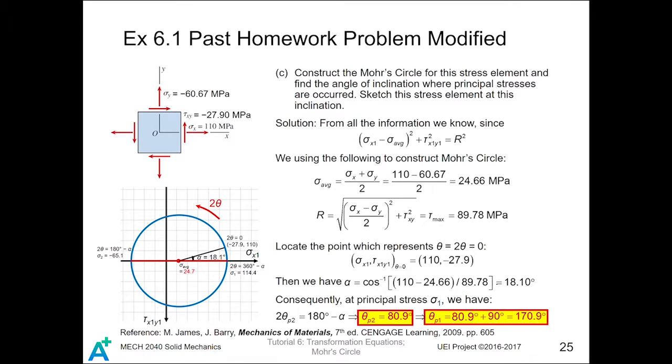Next, by using the results in the previous slides, you are going to construct the Mohr circle for the stress element, as well as find the angle of inclination where the principal stresses occur. You're also going to sketch the stress element at this inclination.